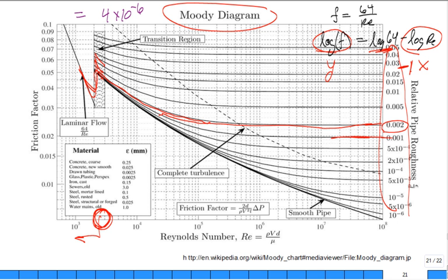But for the laminar, we just did it for a smooth tube, and so now it transitions, and now you have to figure out where you're going to go to. This is kind of a no man's land. There's not a high level of confidence in the friction factor in this vicinity where it's transitioning between laminar and turbulent flow. What would affect it? Little vibrations in the laboratory or in the machine room or in the building, wherever that pipe is located, that could help it either turn turbulent a little earlier or not. Okay.